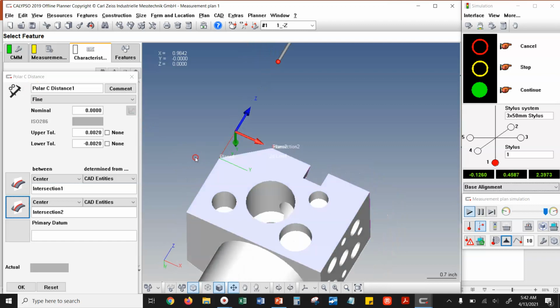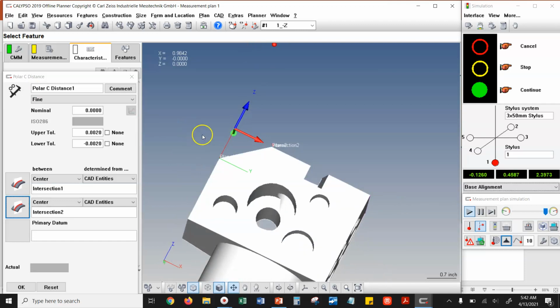And for this measurement, we really want one of the caliper edges to be right here, and another one to be right here. And we want the dial face of the caliper to be here. Right? And we want the rack and pinion assembly of the caliper to be facing that way. Well, if we were to set this down on a surface right now, we'd be setting it on this surface. This is our primary datum.